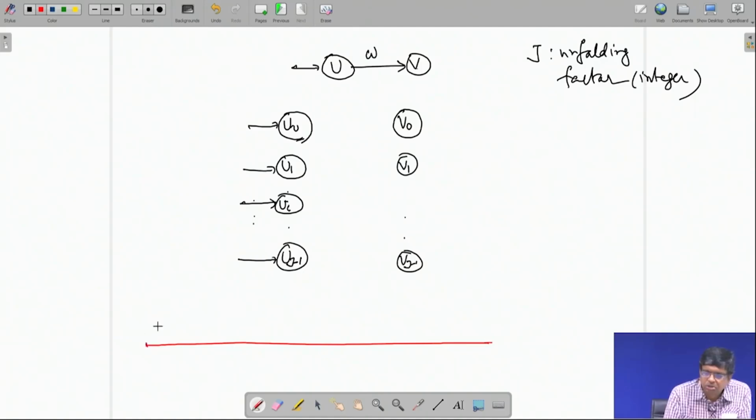If you start at say U0, 0th data, the data at 0th cycle here, then first cycle, second cycle, dot dot dot, they are all parallel. So, data at 0, 1, 2, dot dot dot up to j minus 1. Here they are coming serially, but because of the buffering they are all parallel and they appear in the system together and processed in one clock. That clock I am calling 0th system clock. So, system clock is slower, it takes j number of input clocks.